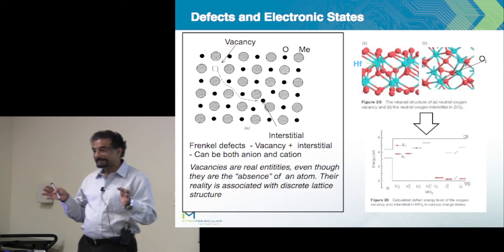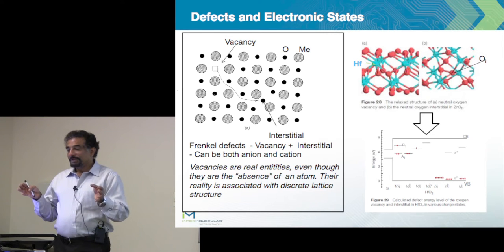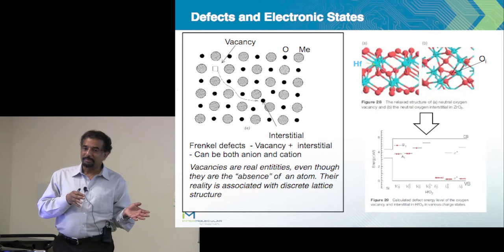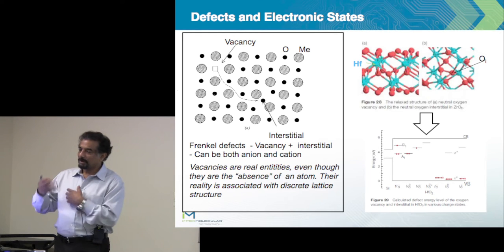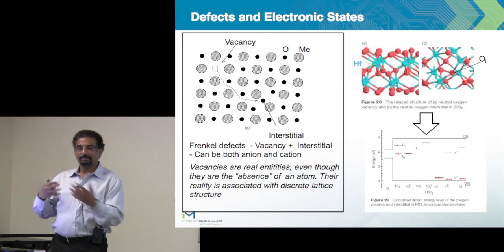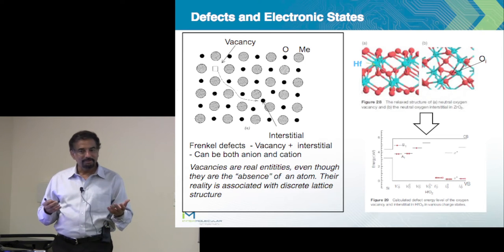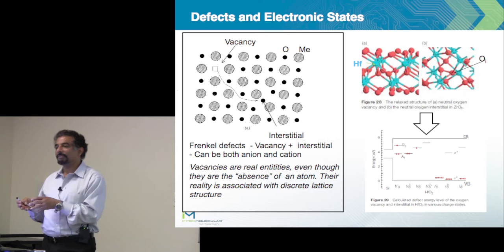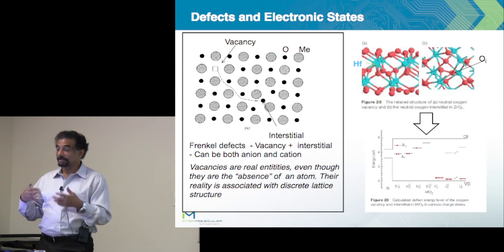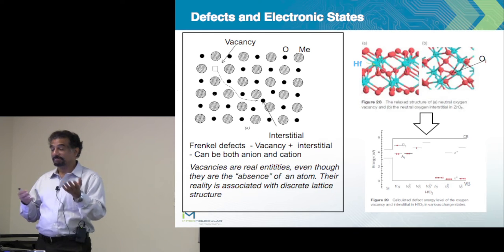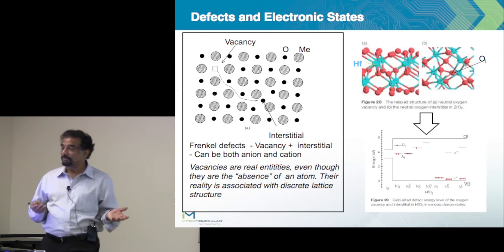And so again, what is required from the material side, because at the end we are talking about electrical devices? Whenever we talk about materials, yes, we want to talk about transformations, we want to talk about what happens, but in the end we still have to talk about electrically what is the impact of them. Does it increase leakage? Does it do something else? Does it change the threshold voltage?